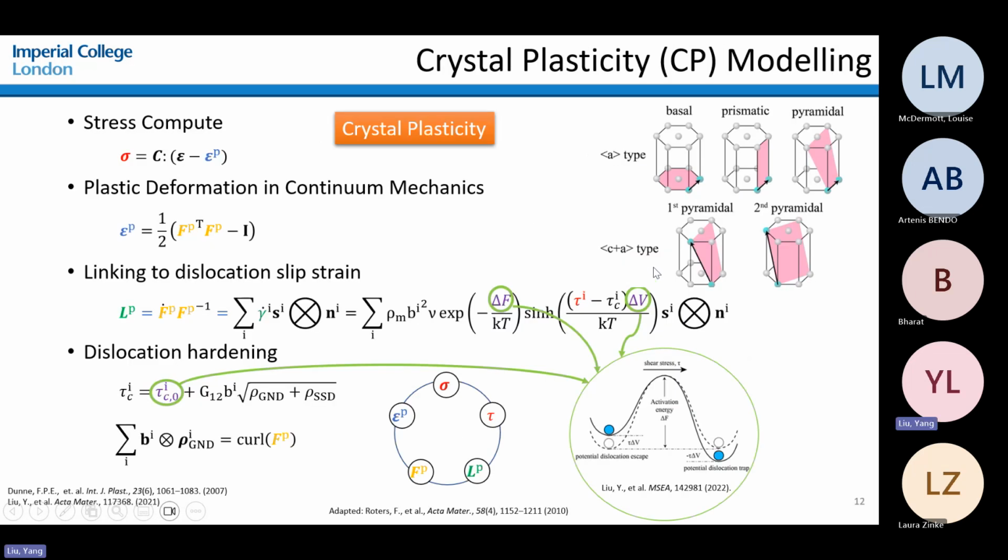And then we applied a crystal plasticity model, which basically you can understand that when the metal deforms, most of the deformation is absorbed by plasticity. And when you want to activate the plasticity in the material, it's activated through different crystal slip systems, where these slip planes would activate specific directions of the dislocations that can accommodate the plastic deformation within the material.